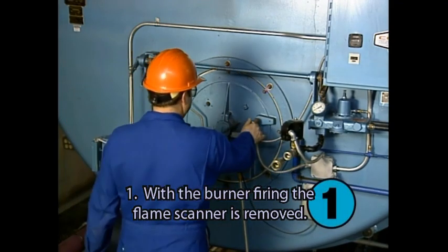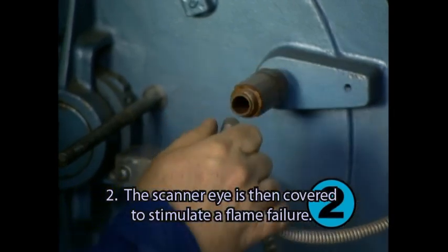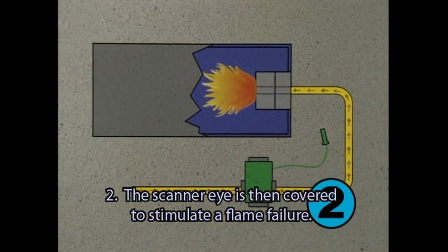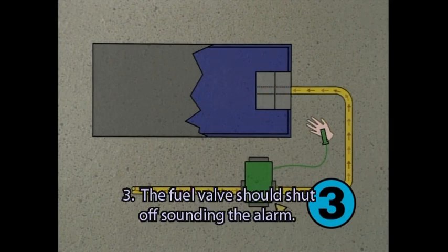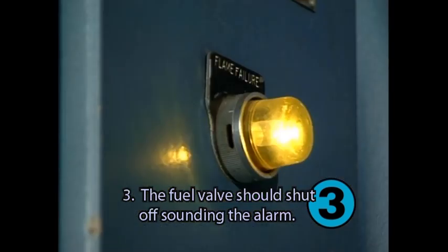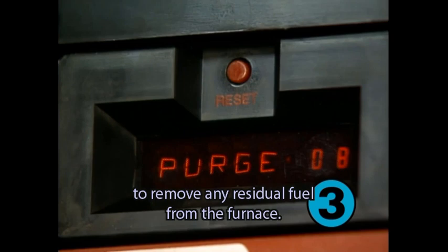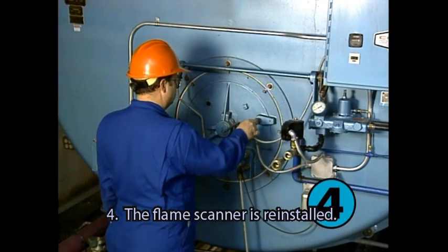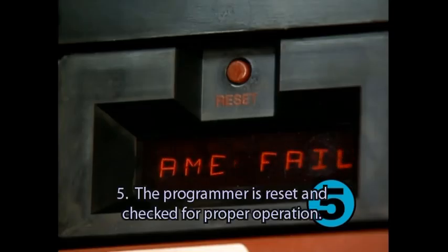1. With the burner firing, the flame scanner is removed. 2. The scanner eye is then covered to simulate a flame failure. 3. The fuel valve should shut off, sounding the alarm. The burner control should begin a post-purge cycle to remove any residual fuel from the furnace. 4. The flame scanner is reinstalled. 5. The programmer is reset and checked for proper operation.